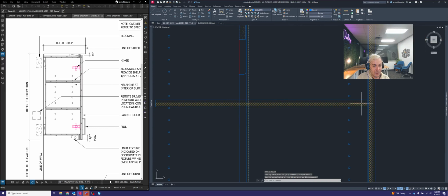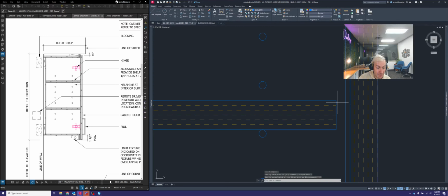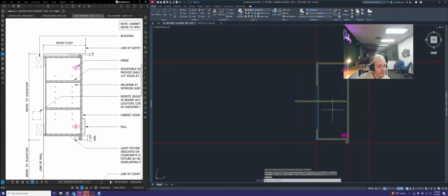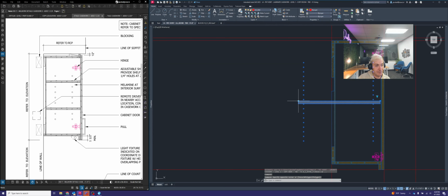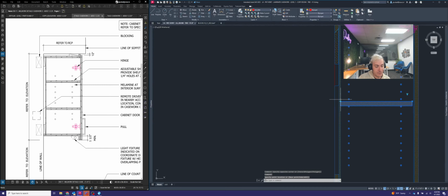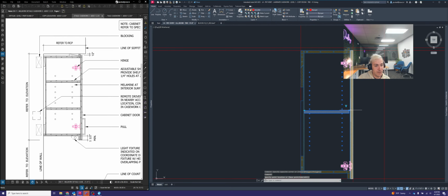And although this upper cabinet doesn't appear to have a white dot for this, we do need to make sure the adjustable shelf is showing a 1/4 inch gap between the front of that shelf and the cabinet carcass front right there. So 0.25. I'm going to adjust the depth to there. And then I'm going to adjust the number of shelf pins a little bit. I'm going to undersize that to 12.